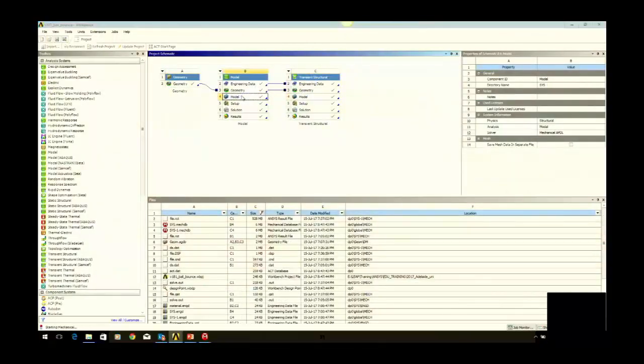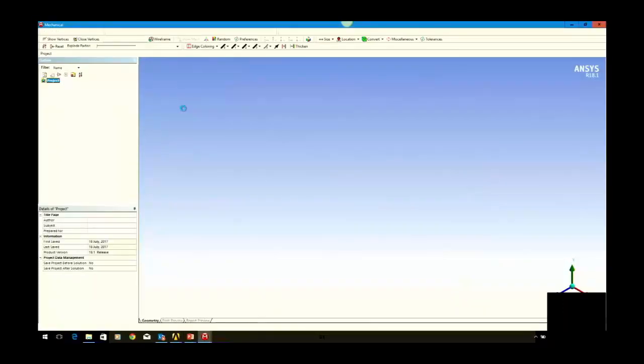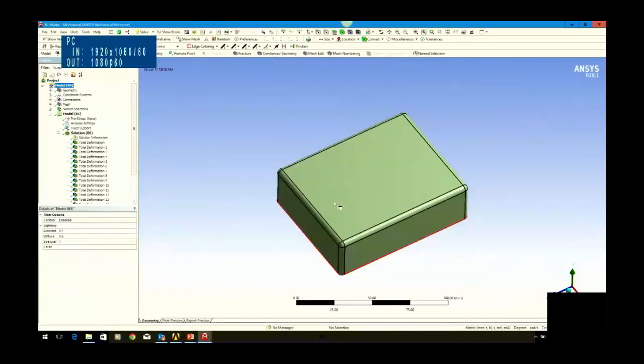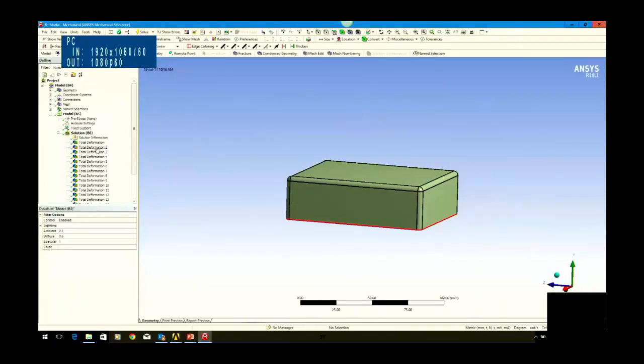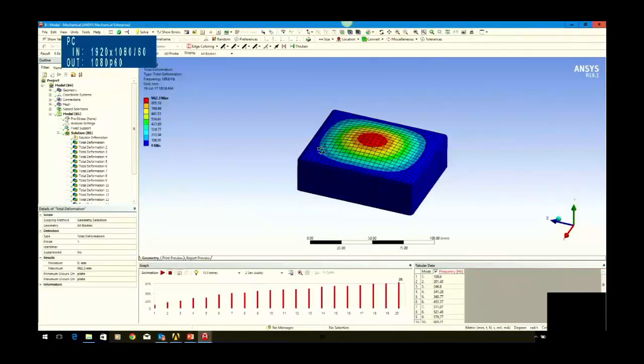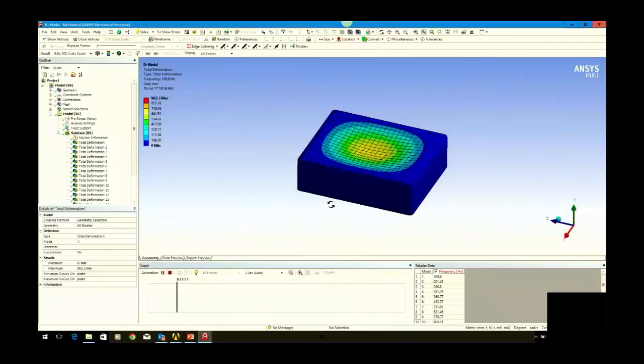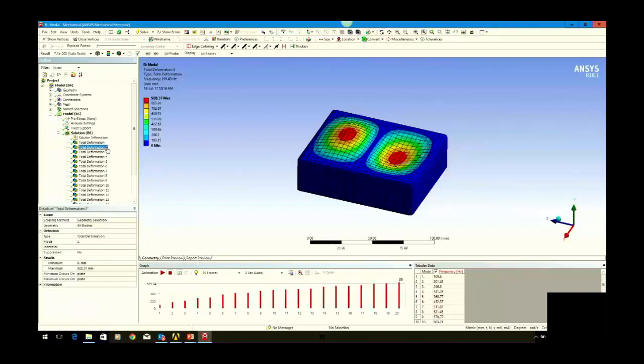So if I go back to my modal analysis that I did as a base for this, using that I determined the time step size that I should be using. Okay, if you look at some of these waves, because the ball is hitting in the middle, it's highly likely that that mode is going to be excited, and that displacement is going to be in the output.